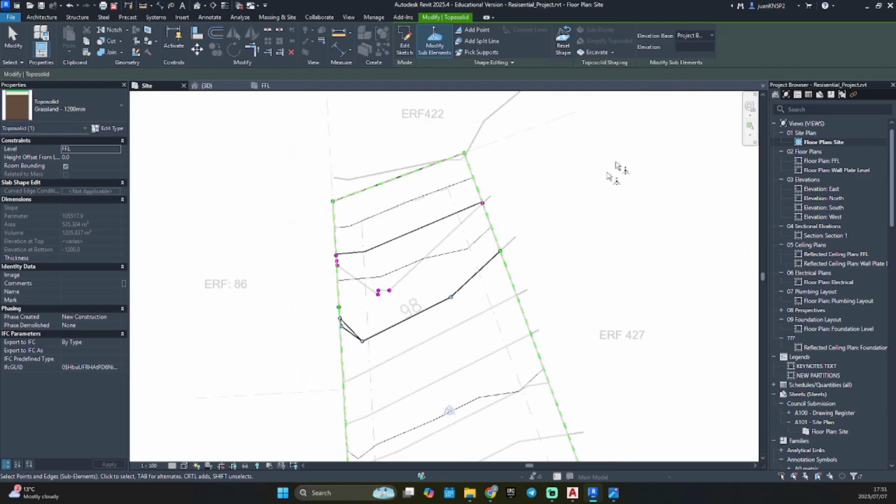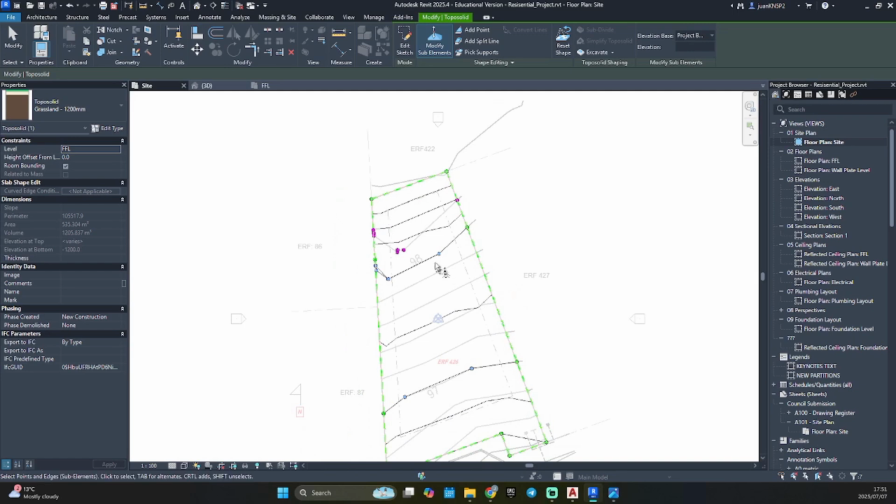Select those points. Now the interval is 200 from our 98 to that contour. How do we know it's 200? Because from this 1 meter, there are 1, 2, 3, 4, 5 lines. And divide that by a meter, it's 200 millimeters. So this will be 1.2 in elevation.